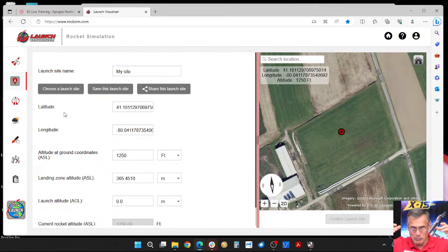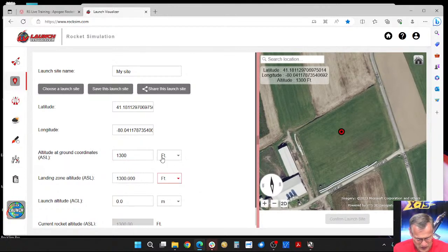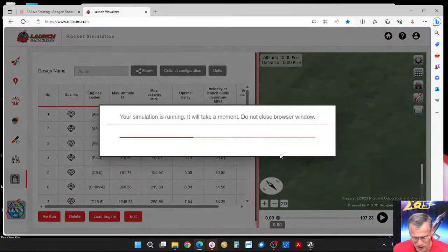And Bing has their own mesh globe. And so we have Bing's mesh Earth surface up here and our mesh surface down here that we're using to run the simulations. And when they don't match up, the rocket appears underground between the two layers. So if you want it to appear above the ground, you've got to change your base altitude here. You just got to keep doing it until the rocket appears above the ground.